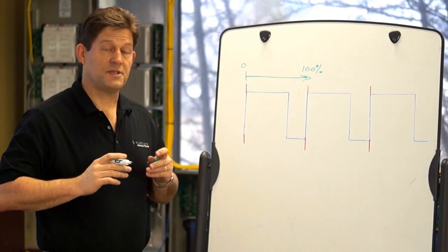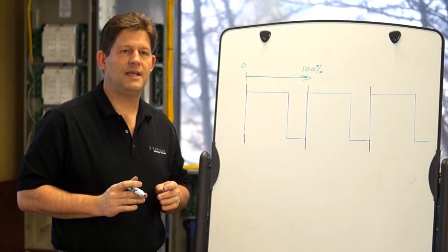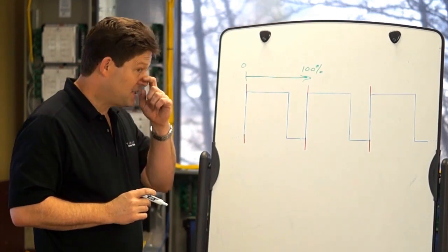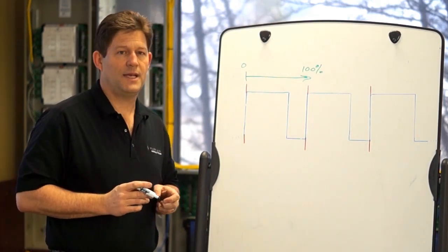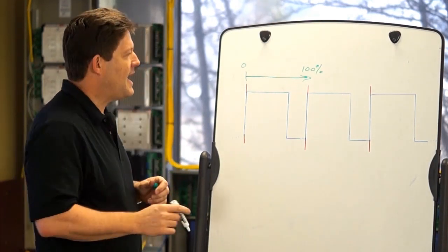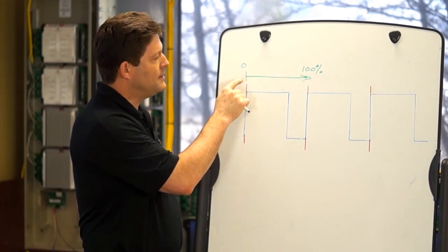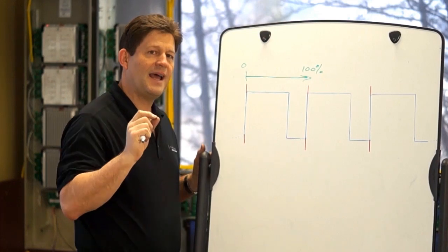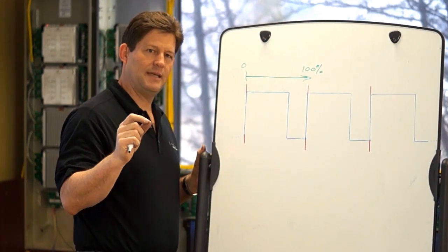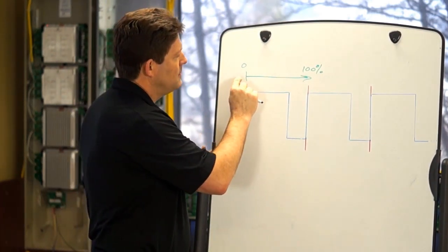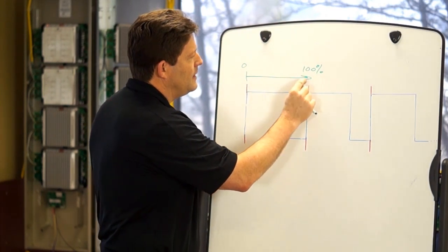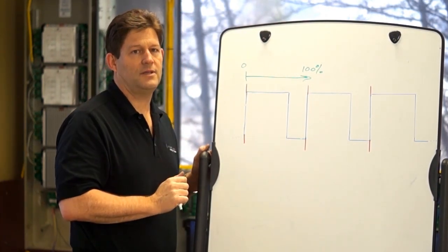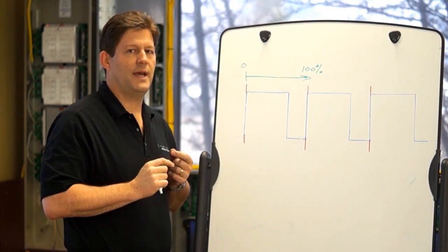Now, there is a standard that applies to dimming pulse width modulated controlled light sources. And that standard is actually opposite of what you might expect. Meaning that if I were to apply the voltage 0% of the time, then the light output is going to be at 100% and reduce down linearly to 0% when we apply the voltage 100% of the time. Opposite of what you'd expect.